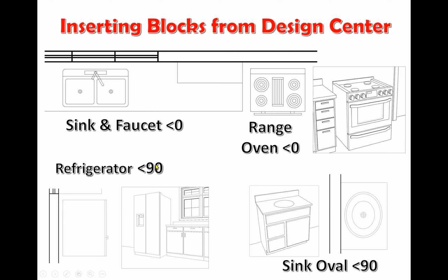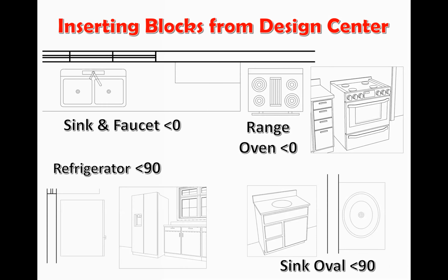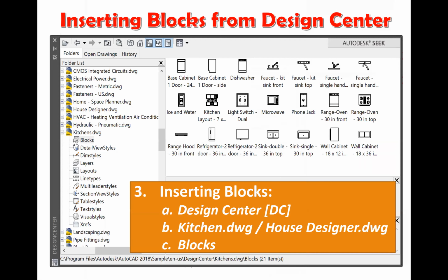Now we're going to have to rotate the refrigerator. These blocks are not dynamic blocks, so they will not give us the ability to just align them to the surface like we did with the previous ones. So we have to learn how to rotate these blocks, right? Whether before we start the inserting or while we're inserting, we can still do it. Okay, so let me go back to the previous slide and I will start talking about the design center.